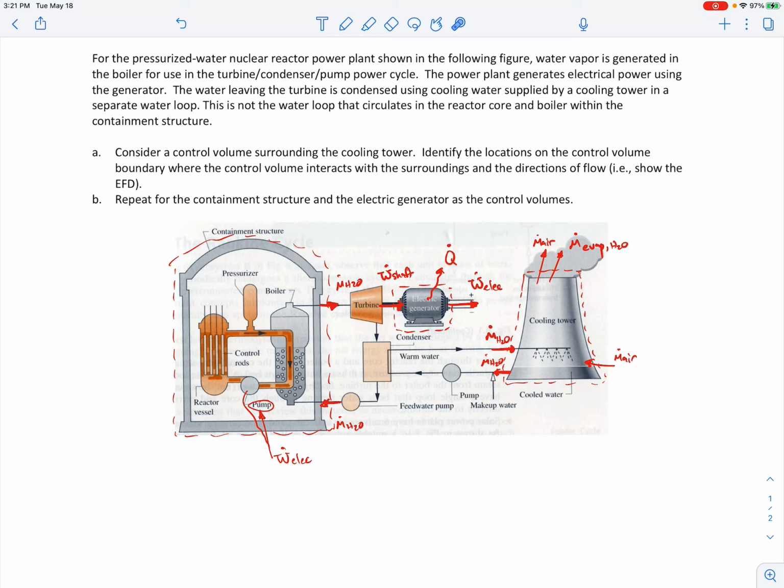And just a reminder, we draw these energy flow diagrams like what I've shown here in these three different devices. We draw those because once we've drawn them, then we start writing out equations for conservation of mass and the first law and the second law. It's very equivalent to drawing free body diagrams and then applying Newton's second law to those free body diagrams. So it's the same exact idea, except instead of dealing with forces, we're dealing here with energy exchanges and mass exchanges. So we start our analysis with these kind of drawings first, and then our equations are based on the drawings. Okay, we'll end the example there.